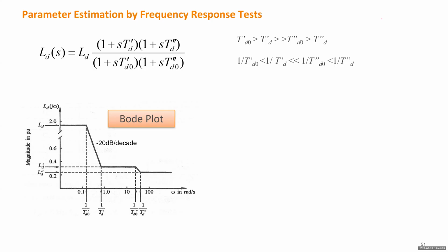Okay, so this indicates there's going to be a pole, which is this one. So the transfer function first experiences a pole, which has the smallest frequency value, and then when you increase the frequency, the next one will be 1 over TD single prime, which will be this one, which is on the numerator, which means it will add a positive 20 dB per decade.